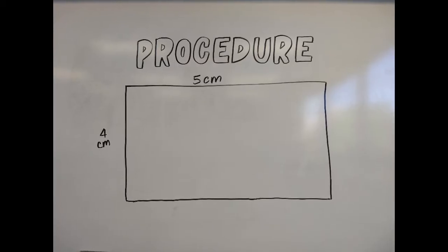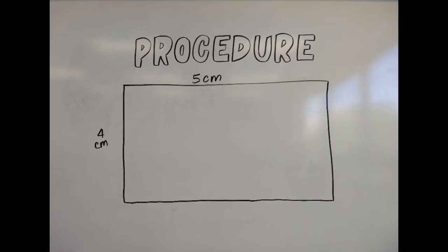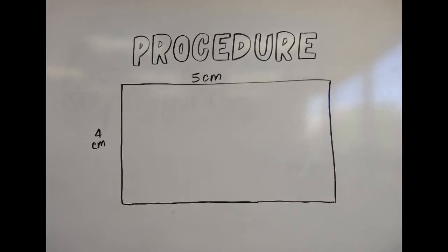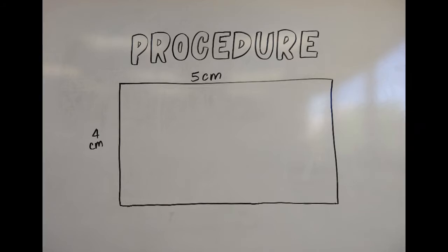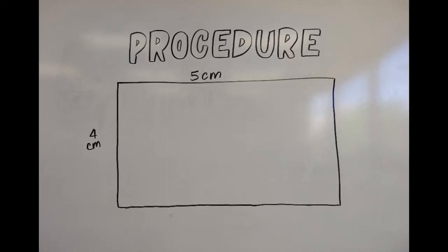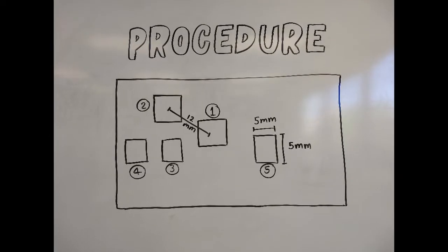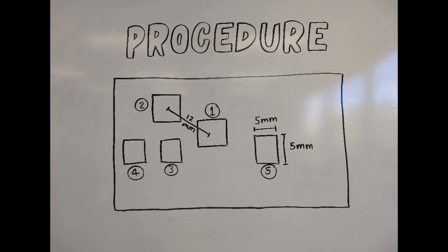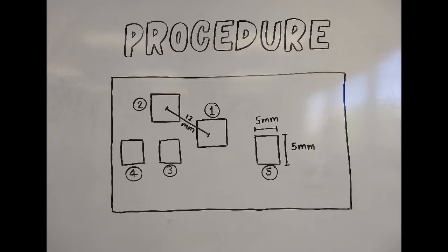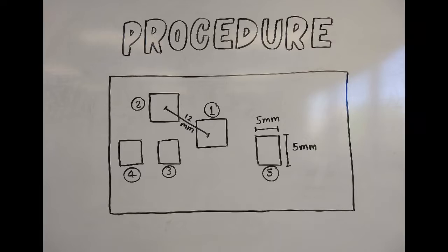We built this circuit according to the schematic shown earlier using step-by-step instructions posted online by Make. We used the copper board instead of a breadboard because breadboards have too much noise at high frequencies. Cut the board to a reasonable size and cut out 5 small pads, gluing them on using the crazy glue as is shown. All connections will be made using soldering.